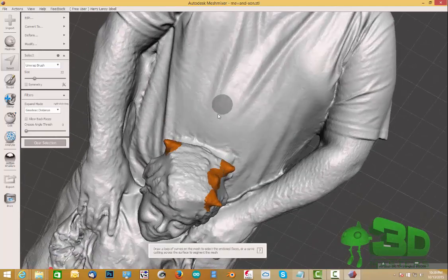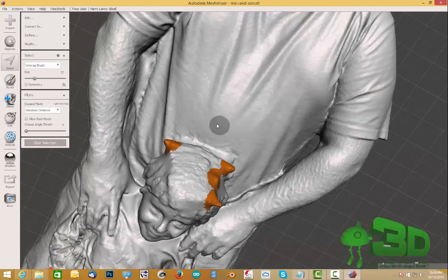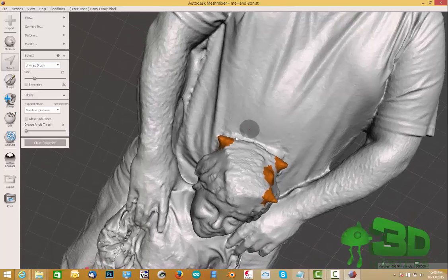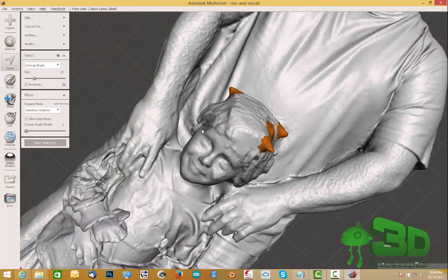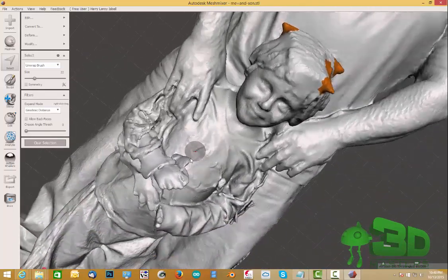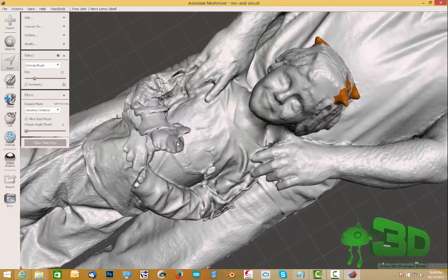And let's move around. Whoops. That, by the way, is a feature called Grow. What I'm doing is holding down Control and the right mouse button and moving it, and it will grow those selections. So we don't want to grow them right now. All I'm looking to do is move this around so I can select more of the objects I need to get rid of.